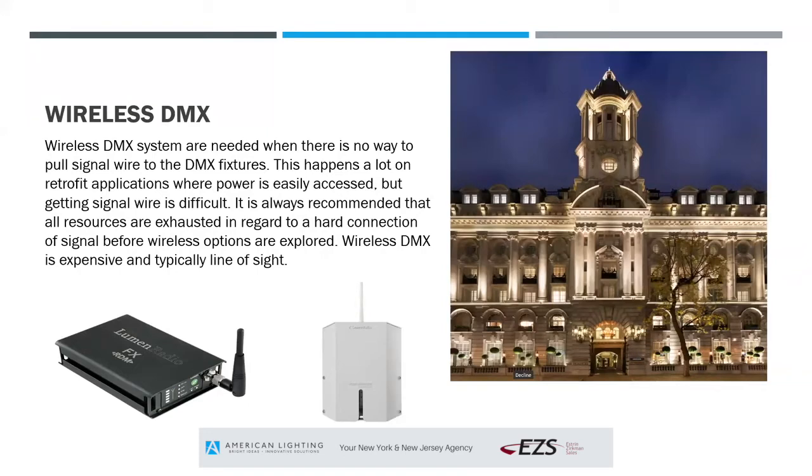You might have existing power because it's an old historic building like the picture shows, and there may be power located there, but because it's historic, it limits what the contractor can do as far as cutting holes, drilling holes, tearing out plaster potentially inside, or who knows what's going on. So you may not always be able to get a hard DMX connection. So there are wireless solutions out there.